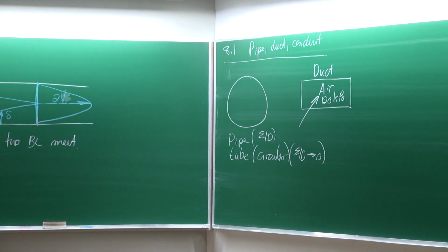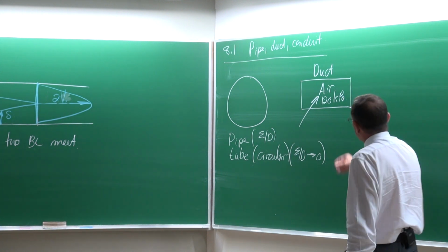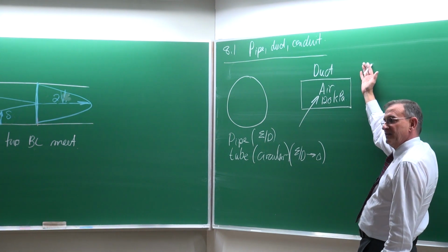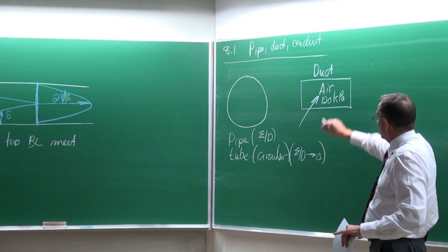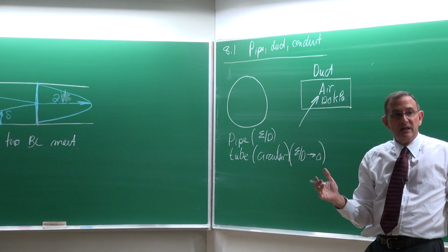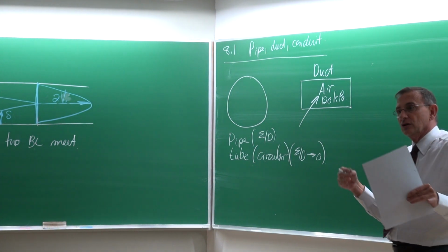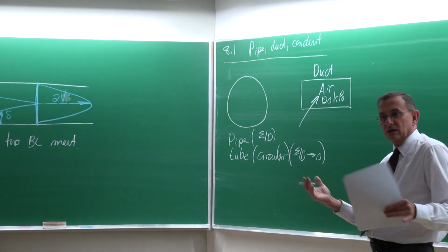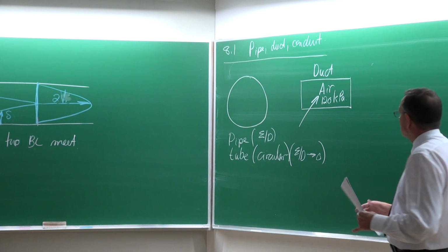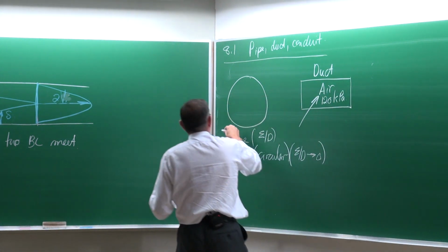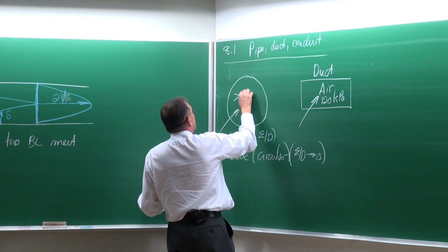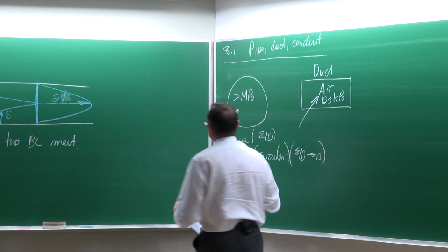They normally carry air, and the pressures in them are normally a maximum of 120 kPa. So they cannot take large pressure differences. If this pressure is becoming higher and higher relative to that of the atmosphere, then there's a huge pressure difference. There's a huge area normally involved, and with a large area, if you keep on increasing the pressure, it increases lots of stresses and strains. With a pipe, however, in most cases, the pressures can go up to megapascals and even more.